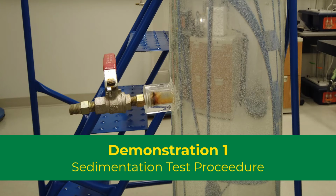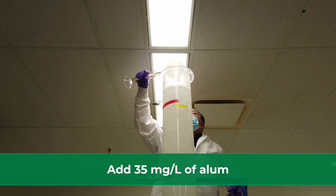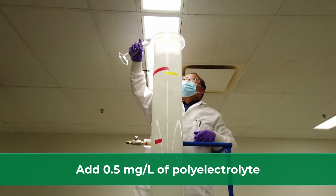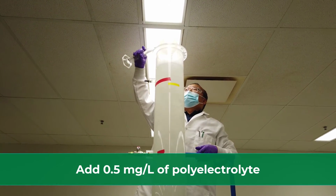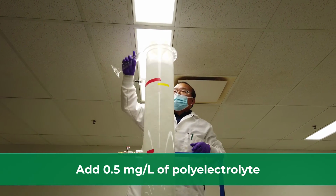Each group will be assigned one of 3 sedimentation columns containing 42.6 liters of untreated water sample. A continual stream of air will be passed through the column to ensure that the particles remain suspended. Add 35 milligrams per liter alum, with an initial concentration of 10 grams per liter, first, and then 0.5 milligrams per liter polyelectrolyte, initial concentration of 100 milligrams per liter, to the top of the column while mixing with air.